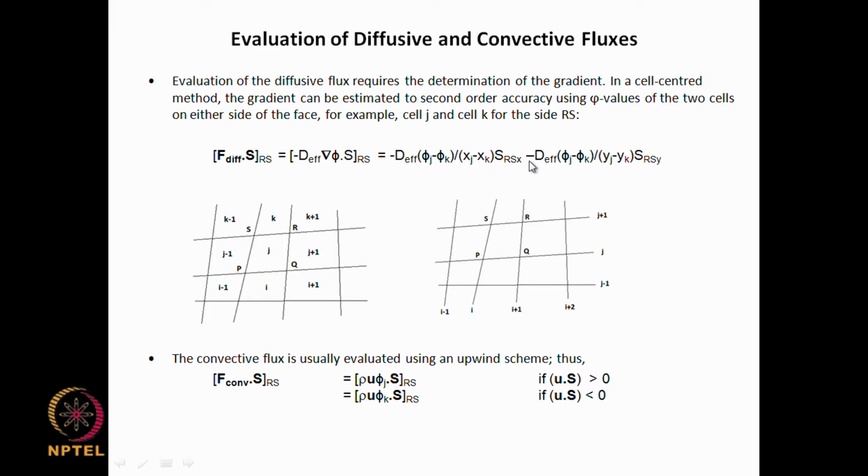So, times S_RS x, the x component of the surface vector, and diffusivity times phi j minus phi k divided by y j minus y k, this is the y coordinate here, times the y component of this. So, this can be used for evaluation of the diffusive flux.